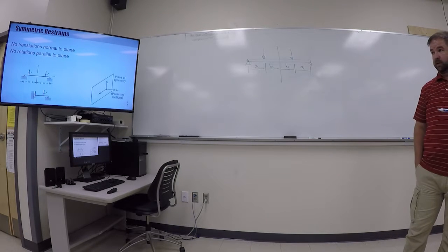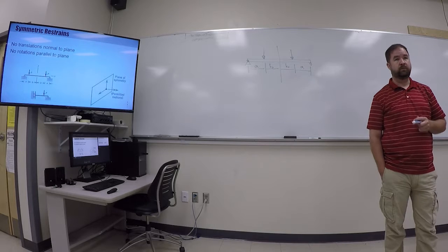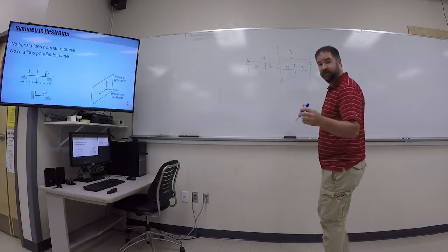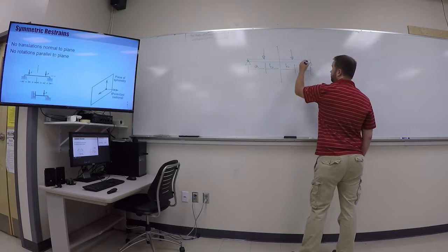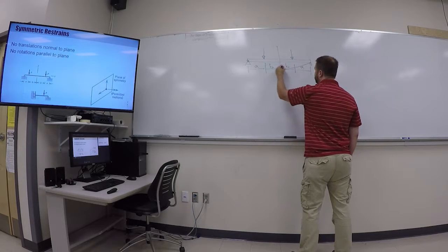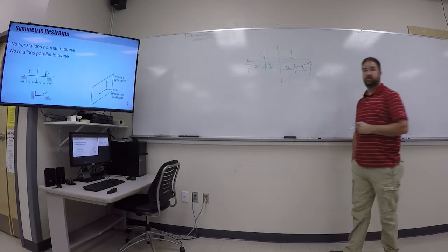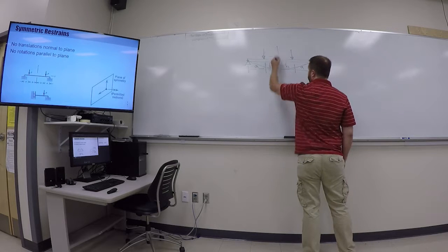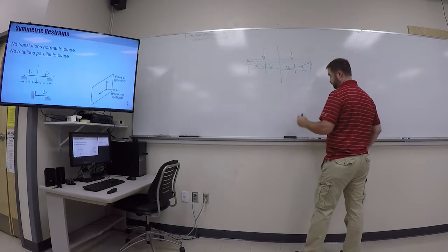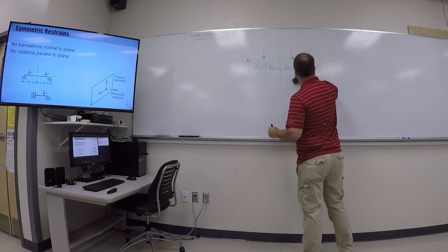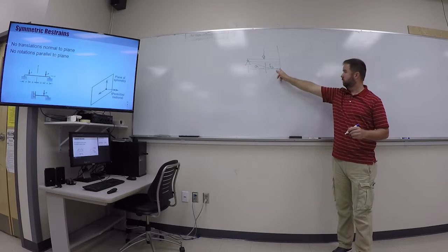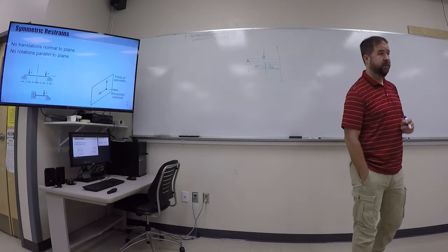When that deforms, what does that look like? What shape does that beam have? Like U-shaped. Smiley face. That was exactly the word I was thinking of, right? What were you saying, Eric? Oh, U-shaped. Okay, U-shaped. So the deformed shape is going to be something like that, right? Okay? If I cut this in the middle and I erase half of this, what has happened there on the end?